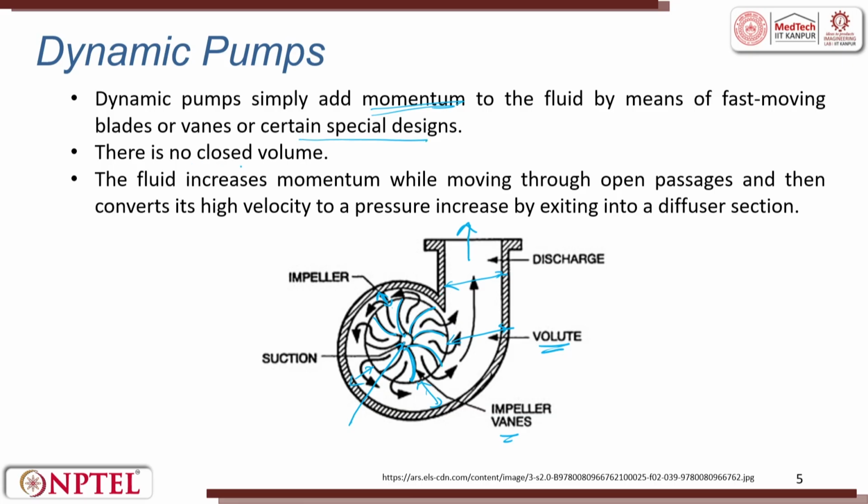There is no closed volume. The fluid increases momentum while moving through the open passage. This is an open passage and converts its high velocity to a pressure increase by exiting into a diffuser section.